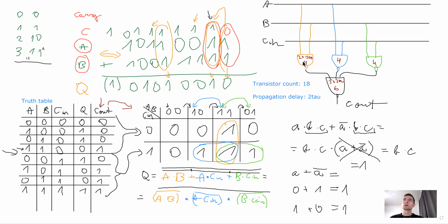So we generalized our transistor connections to these gates. I didn't draw it using transistors. I could have, it wouldn't be that complicated, but at some point it all becomes too much on the screen. So we will generalize these two circuits to some things that we will call 1-bit half adder and carry calculation unit, for example. And if we put them inside the same block, it will be basically a 1-bit adder, a 1-bit full adder.